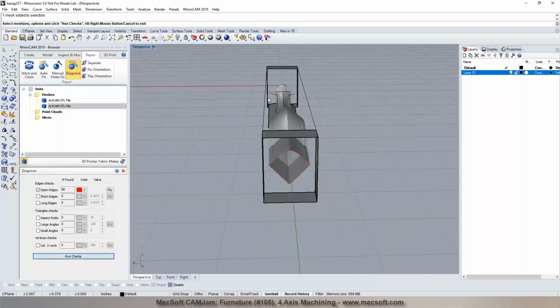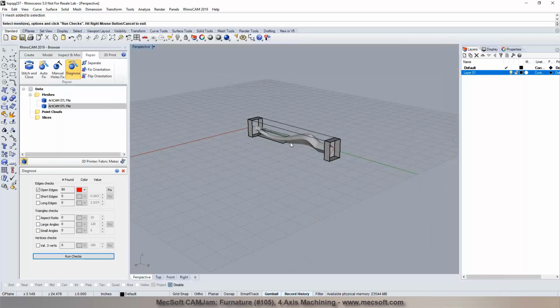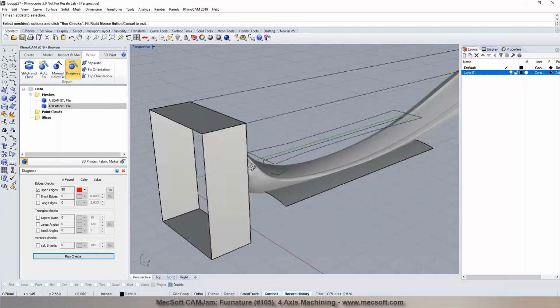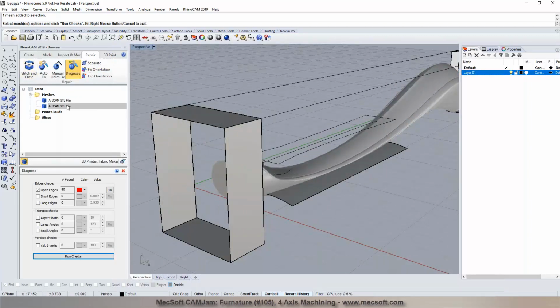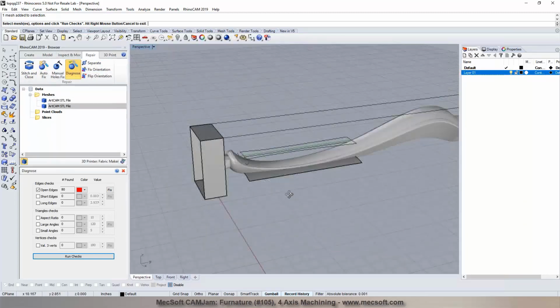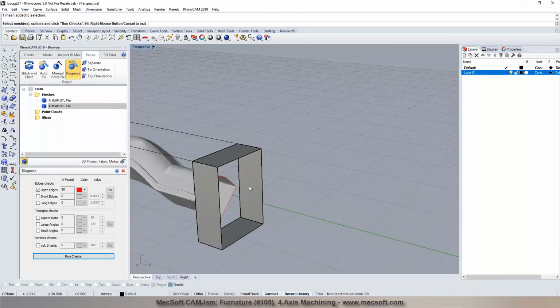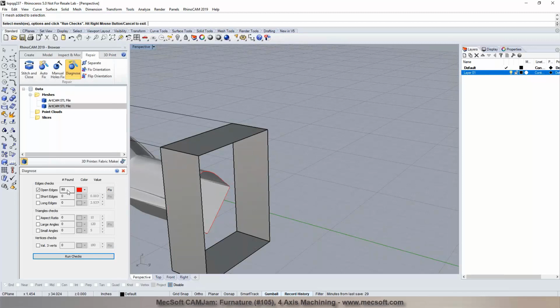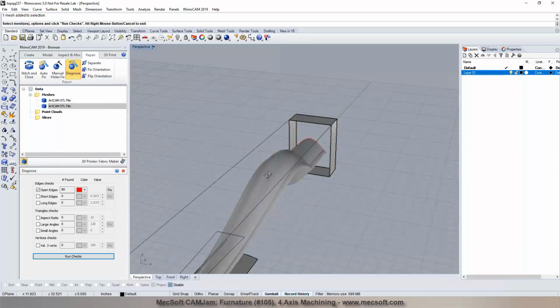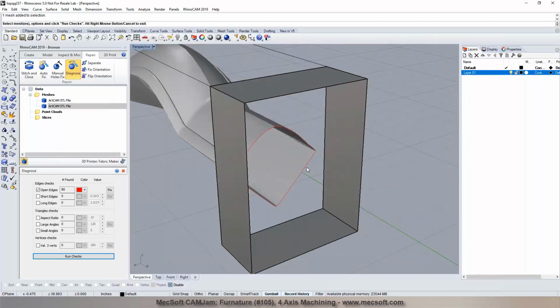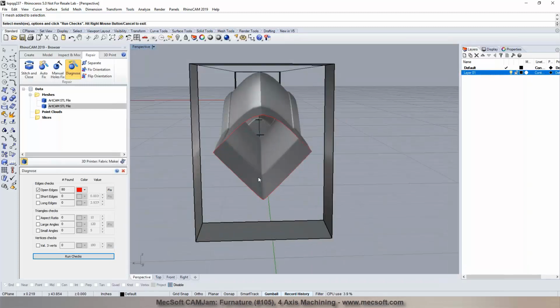Yes, so that's on the demo file. Right. So in the demo, you can't perform any of these tasks because the mesh module requires a license to run any of these commands. And here you can see that it shows there are about 80 open edges right here. In this particular model, it wouldn't make much difference because you're not going to be cutting it from this direction. So the cutter wouldn't be entering in from here.